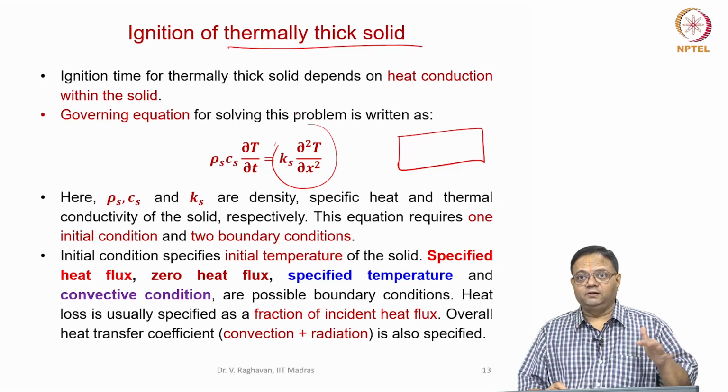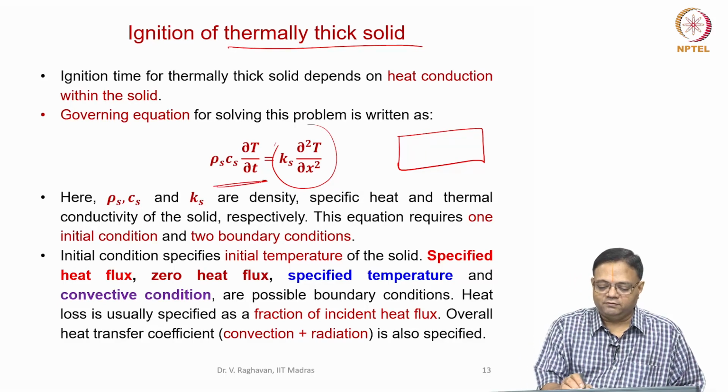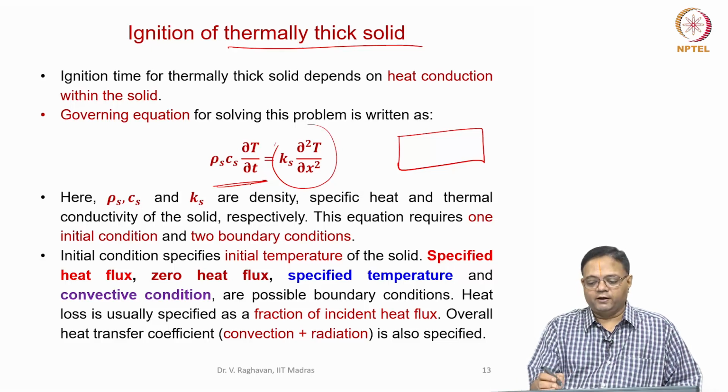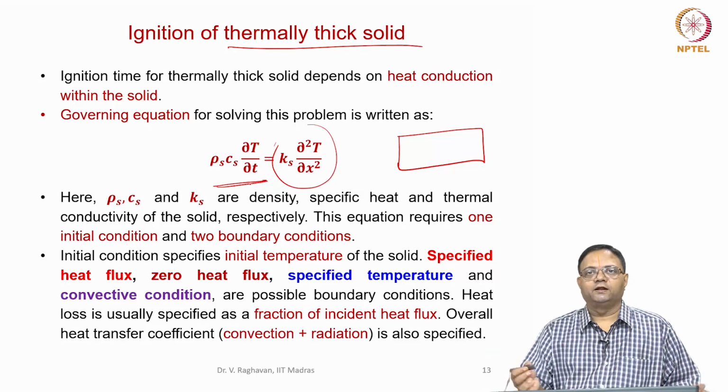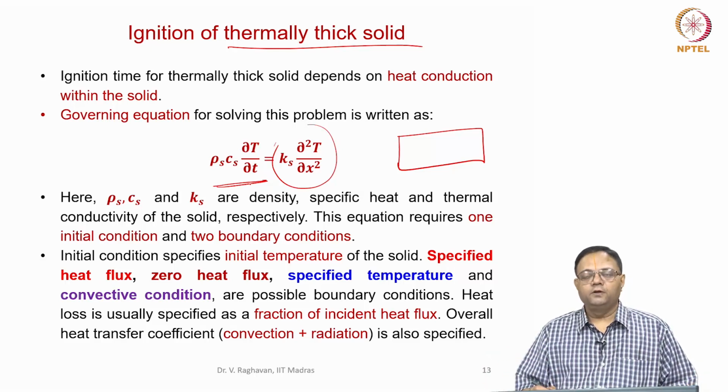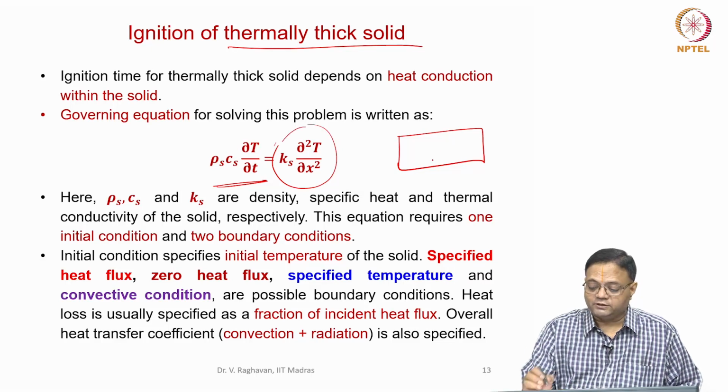If it is thermally thin, then I do not need to do this. For thermally thin, the temperature rise can be equated to some convection loss, something like h into delta T, and I will try to solve this. But in this case, the conduction has to be solved.